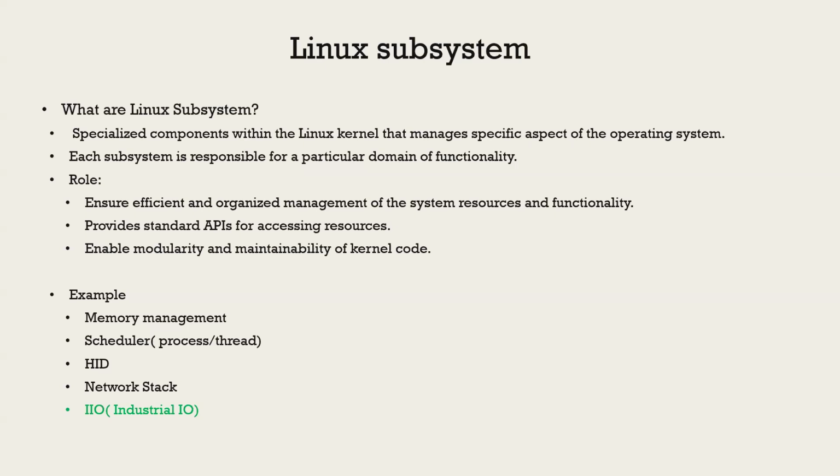That's used by the RTOS. RTOS stands for real-time operating system, and those are meant for small-footprint embedded systems like microcontrollers. There are certain variants of Linux which run on microcontrollers, all called uClinux, microcontroller Linux. They use the LWIP stack, so we are removing the actual networking stack component and bringing in a customized version of the networking stack.